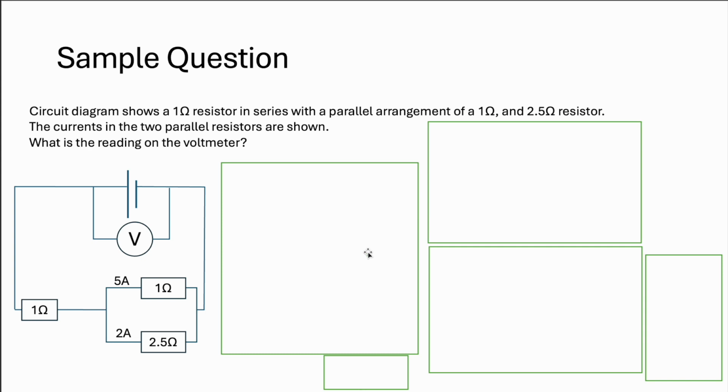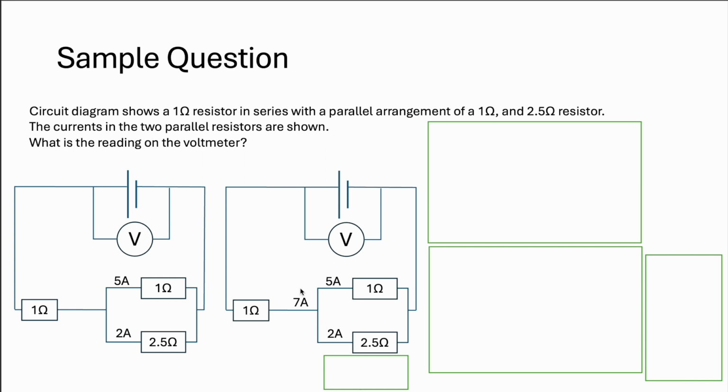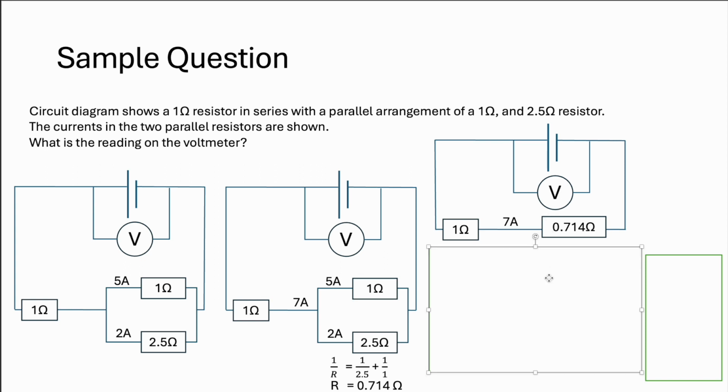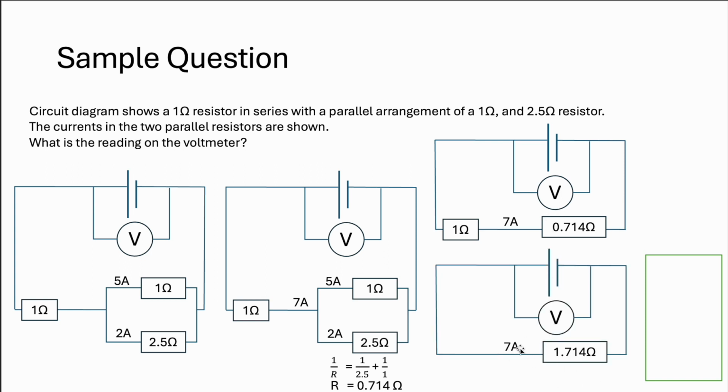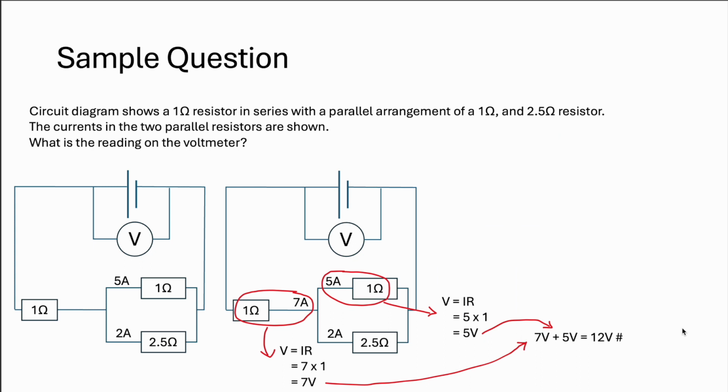Next question. Circuit drawn as shown. What is the reading on the voltmeter? So this is a foundational question. We deal with the current one first. It's easy. So 2 little rivers you join become a big river. Then resistance, you use your 1 over R formula. Then you simplify the branch one. Then you add this summarized stone to the other stone, your other resistor. Then you're going to get this value. Then V equals to IR. You're going to get this answer. So you realize many times circuits are drawn in all kinds of shapes and sizes and fashion. Learn how to simplify them, for parallel resistors especially, or resistors in series. Always help yourself by simplifying them or redrawing them, in fact, to help yourself visualize to your advantage.